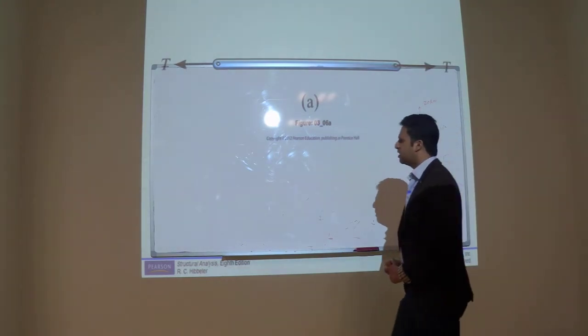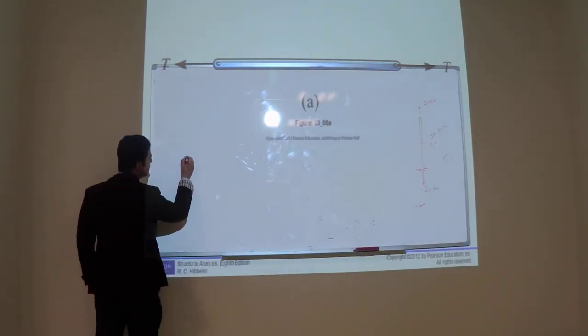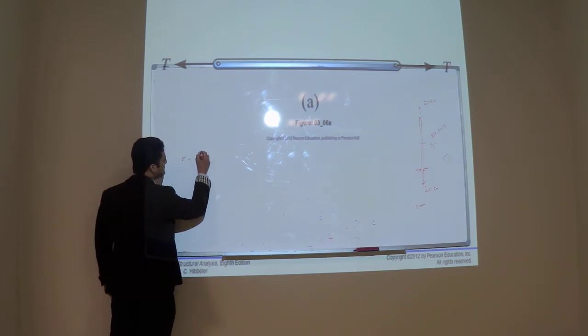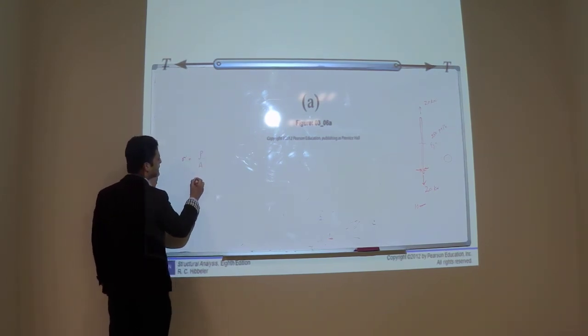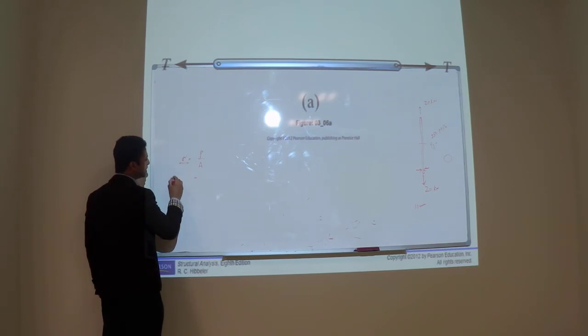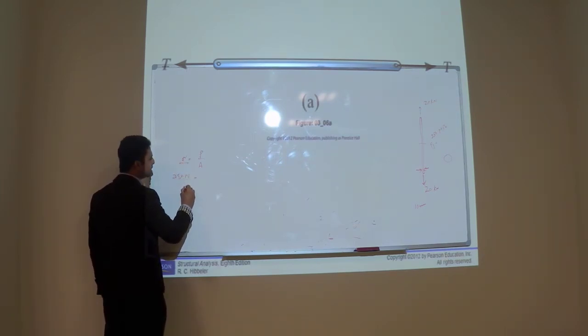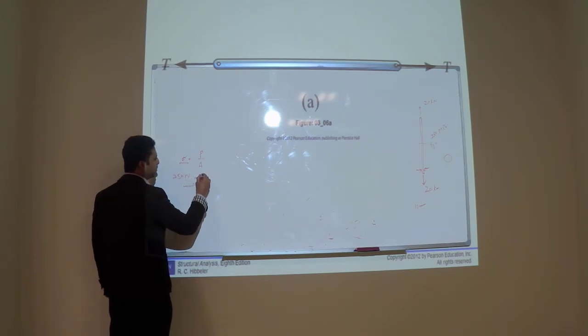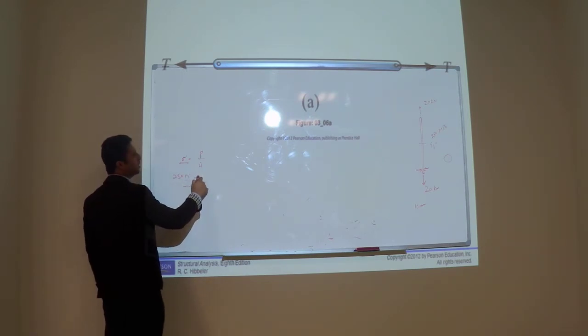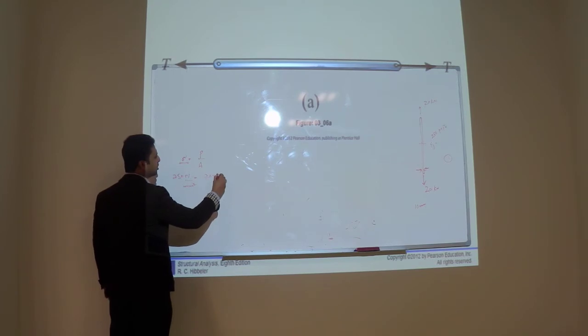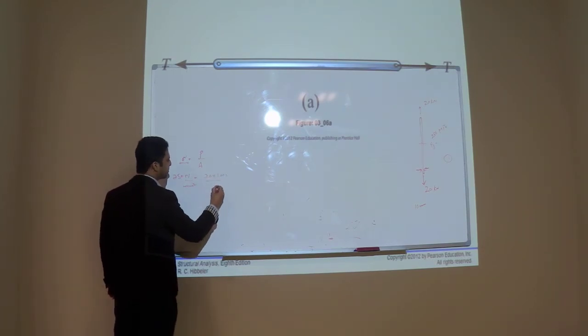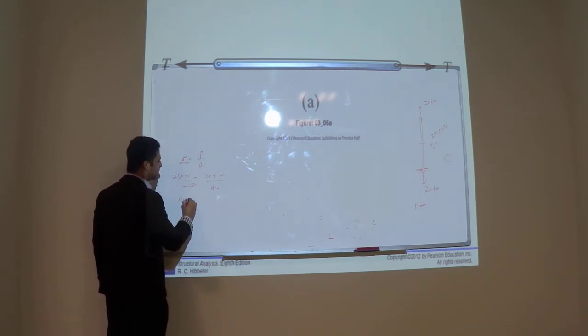It's very, very simple. The stress is equal to P over A. This is the breaking stress, 250 megapascal. Megapascal means Newton per millimeter square. And P is how much? 20 kilonewton. So you need the area. Once you have the area, how much is the area?